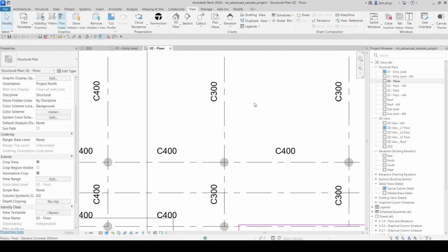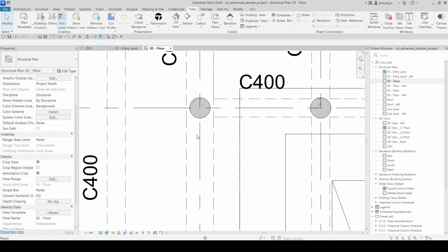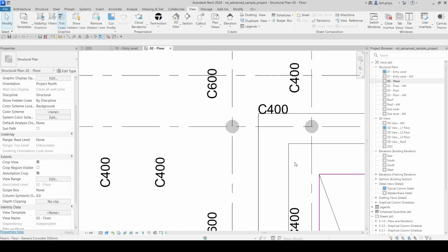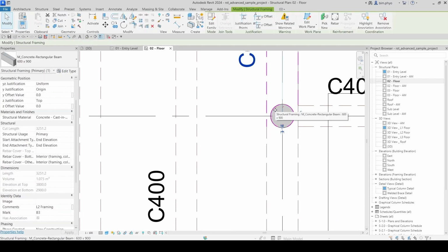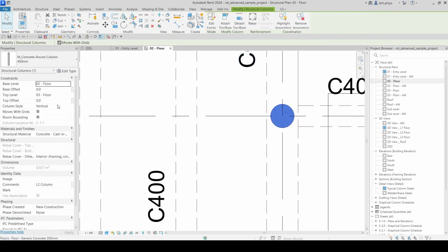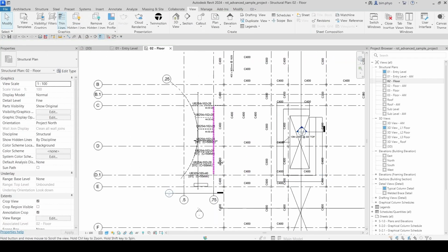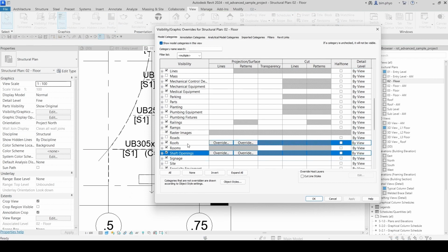Look at this. Okay. How about the column? When we apply the solid in here, we select the structural column in here. Just call the tab for the structural column here. It's going from level 2 to level 3, so we can apply the cut plane to the column.